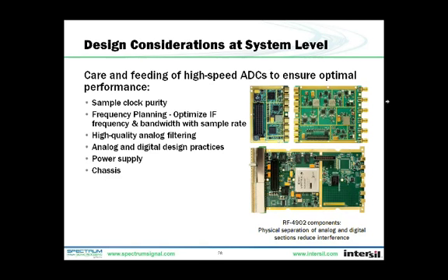Second, frequency planning. You need to optimize the IF frequency and bandwidth with the sample rate.